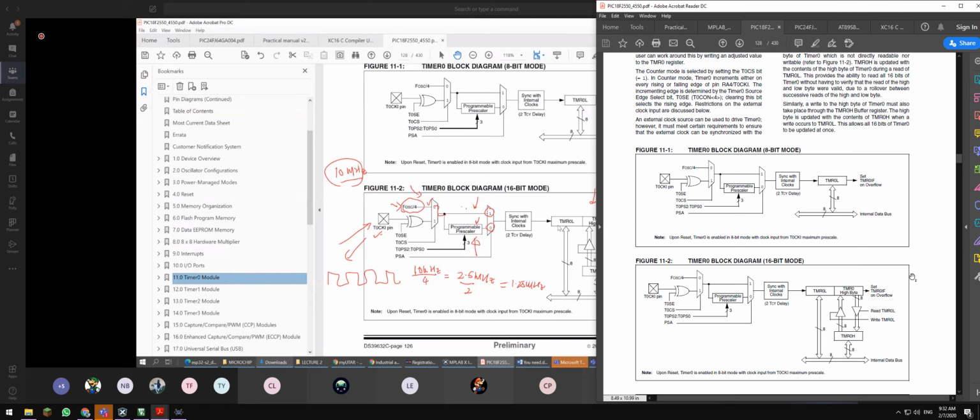Then this one is the delay. Remember, nothing is perfect. Even though you're using a timer to generate 1.25 microsecond, it wouldn't give you exactly 1.25 microsecond. There's a plus or minus. The accuracy is not 100% exactly what you want, it's probably plus or minus 2 to 3 microseconds.